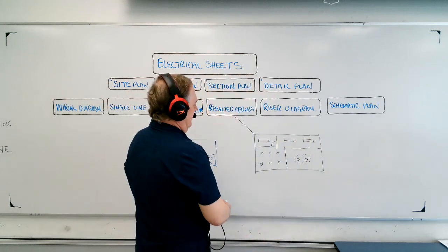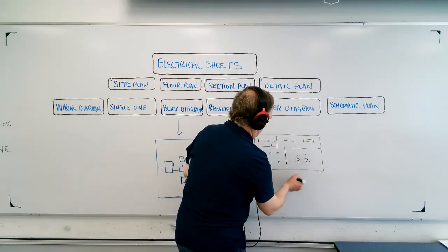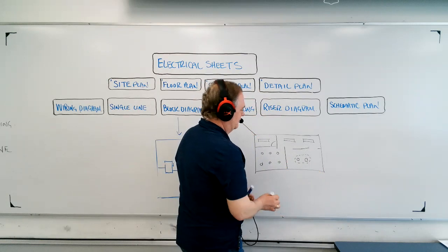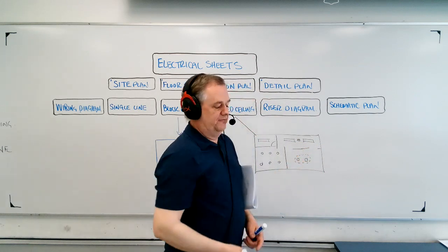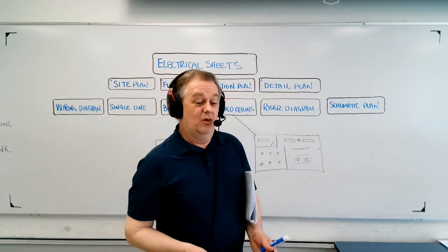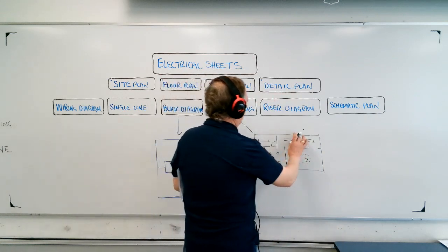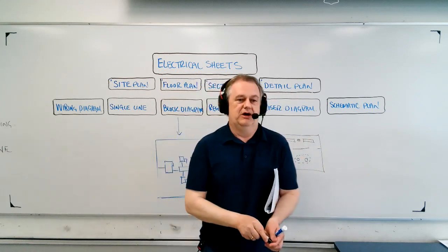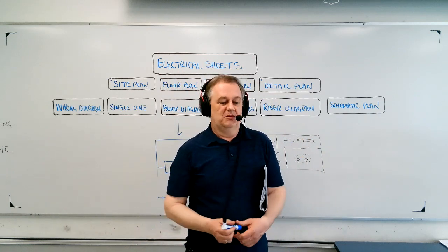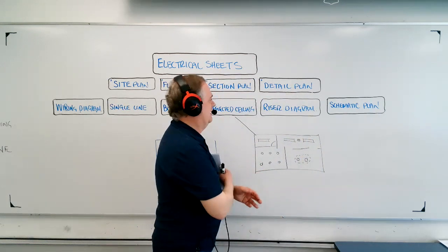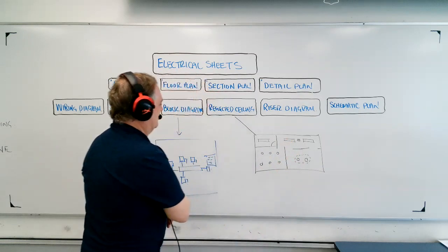Reflected ceiling plan. And what's also very often shown on these types of plans is, just for instance, a bit of a crossover of information, but let's say that there's a diffuser for the air handling system. So you need to know where the diffusers are and things like that so you can work your lights around them. So sometimes there's a little bit of additional information, particularly if you had an architect that's really good with coordinating between different trades. He'll probably put some useful information from another discipline onto the electrical just to make sure things go better. Okay, and that's always nice to see.